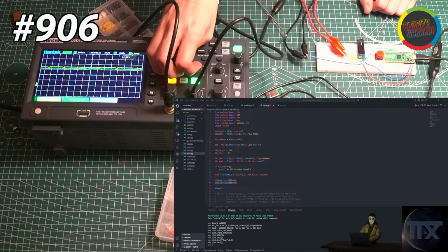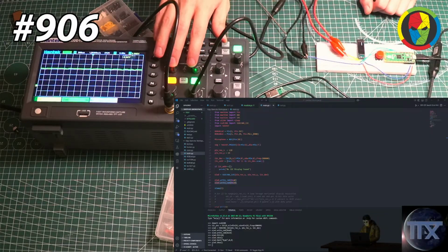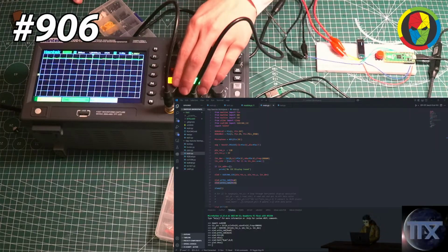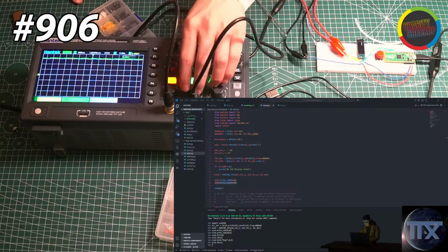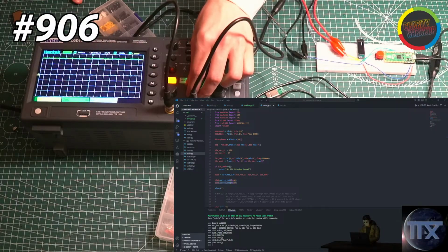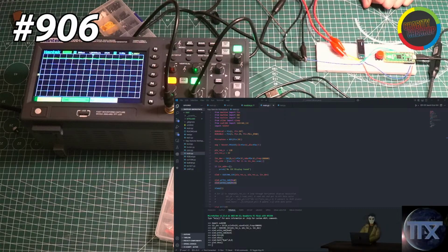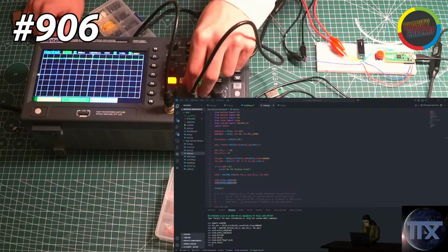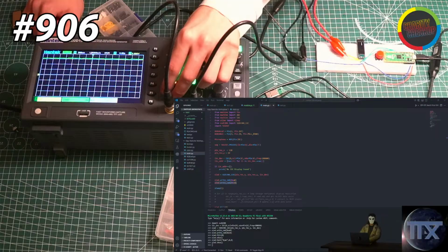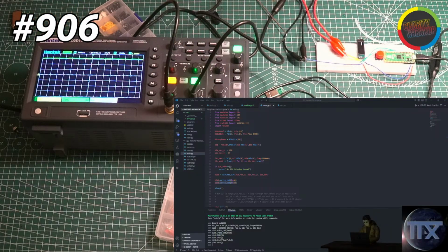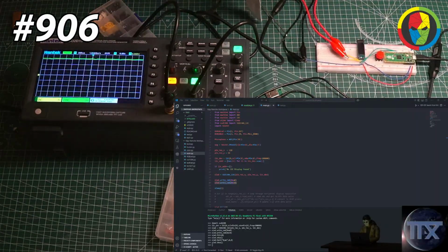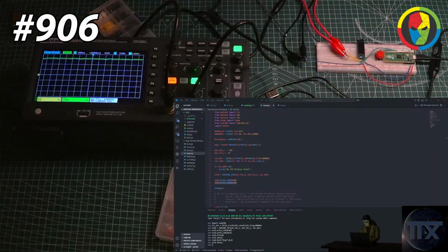Okay, so I will guess that I need both of these lines. Well, I don't need to, but it would be better to have both of them. If you press in those buttons, they have a push in, so push in on them and they reset to 0. Oh, perfect. And then the bottom one is your voltage. The bigger knobs for each channel, when you move those, you'll see at the bottom a voltage symbol, and they'll tell you like 100 millivolts or 5 volts. That's telling you how big the squares are. So if you have it set to 1 volt, then all the squares are 1 volt. So you can just count, that's 3 volts up.